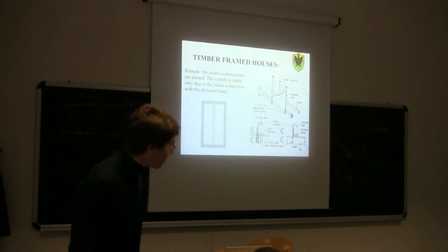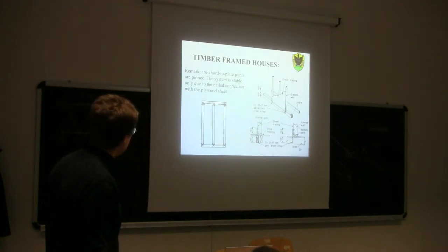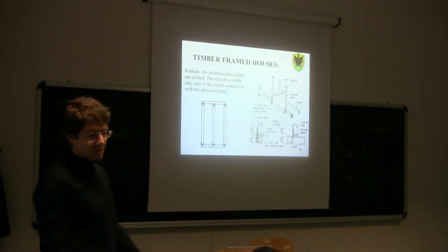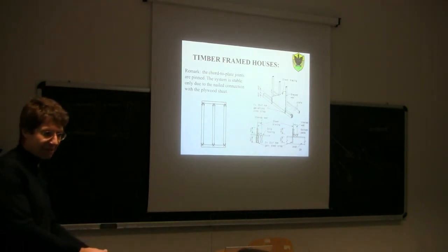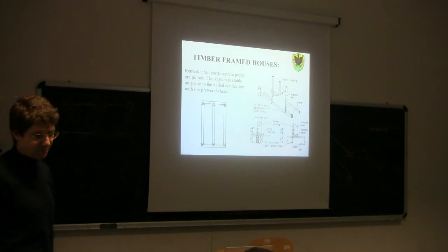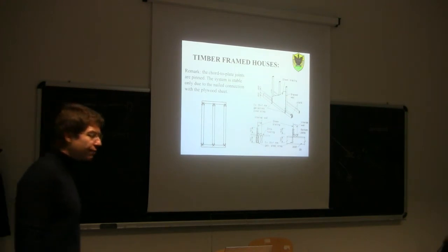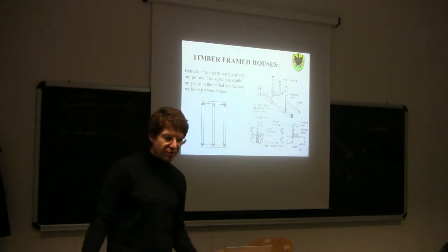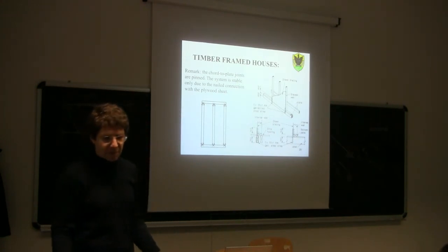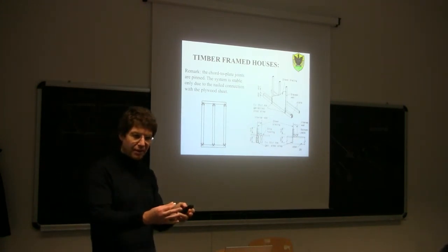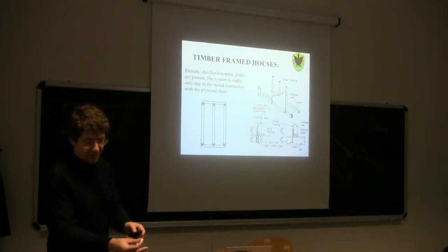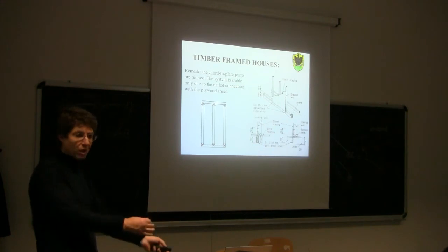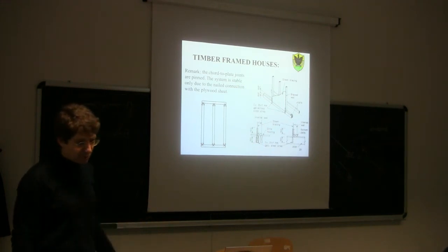Which one? Strictly speaking, it would be semi-rigid, but much closer to a pin than to a fixed one. Very often, when we talk about joints, they are semi-rigid. But we like to classify into either rigid or pinned, depending on whether they are closer to one solution or the other. Which one is much closer to the pin one.